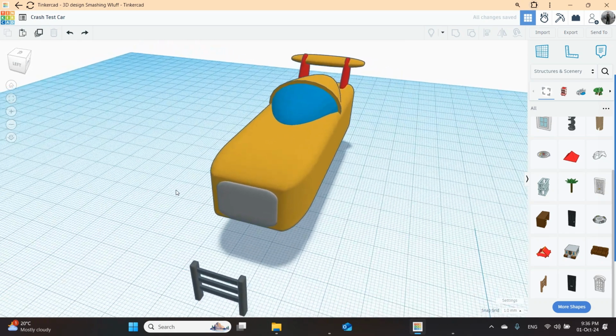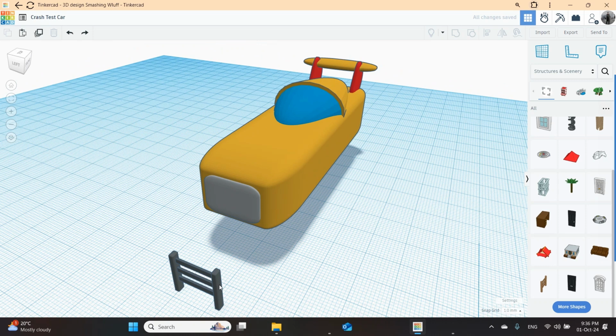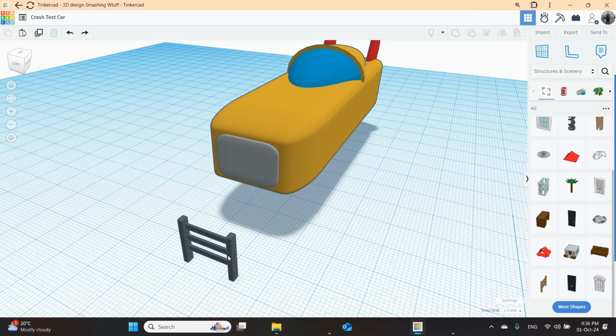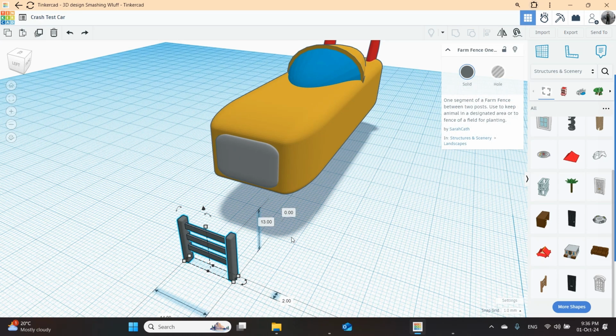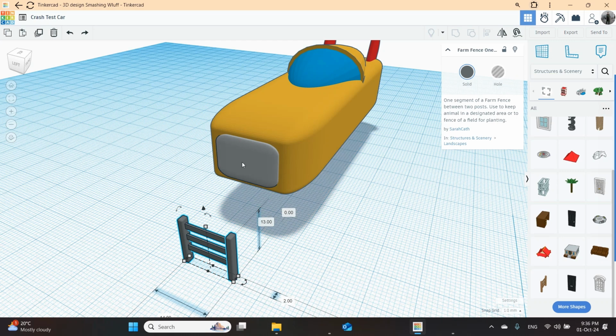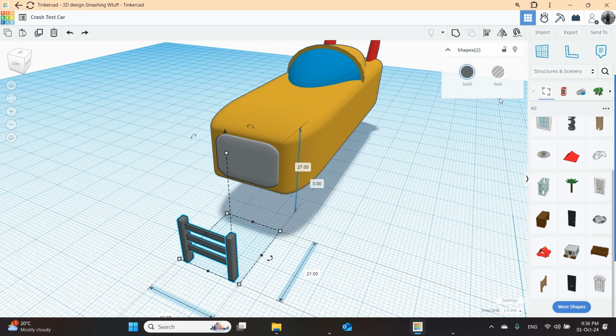I want the shape to come to this part when I am aligning. How will we do that? I will select both shapes using Shift. So I'm pressing Shift, click, click. Okay. Now I click Align. Perfect. But now, instead of going directly to Align, I will go to this shape and I will click it.